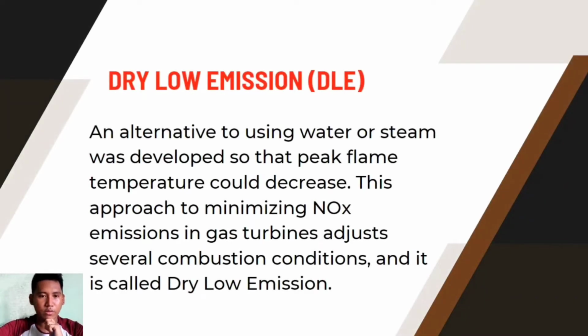Dry low emission or DLE. An alternative to using water or steam was developed so that peak flame temperature could decrease. This approach to minimizing NOx emission in gas turbines adjusts several combustion conditions and it is called dry low emission.